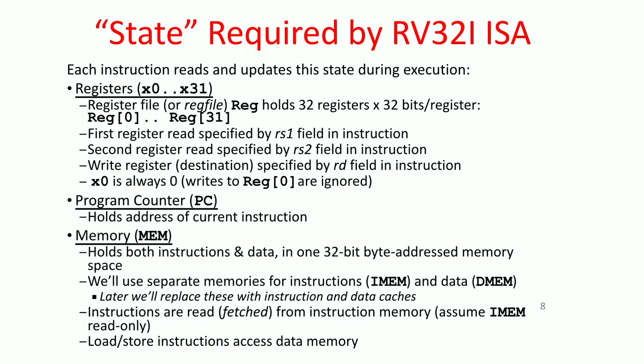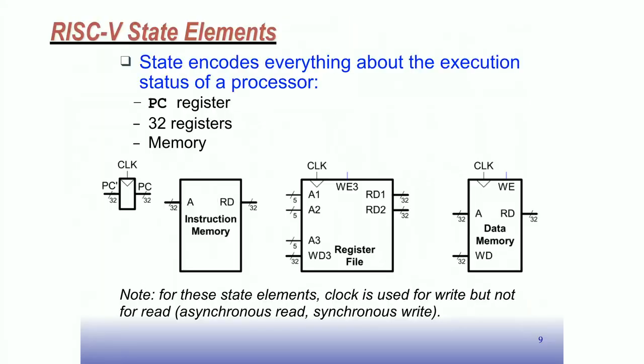So the way software works on RISC processors is that variables from your program get mapped to memory locations. For the ones that are going to be used for a while, the compiler will generate code that moves those operands into the register file as they're being worked on. And then when they're not needed after a while, the compiler will generate code that moves them back to the data memory. This is to use the registers for the operands that are going to be used for a while, the most popular ones. Okay, one more slide.